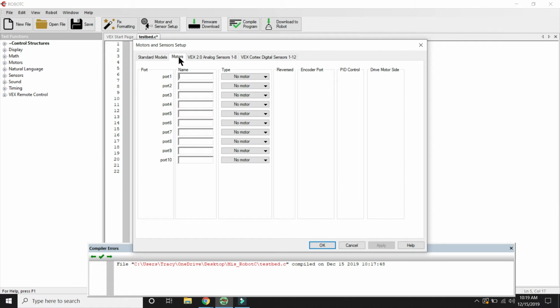So here's the thing. You always start with lowercase, and you can't put any spaces or any special characters, and you have to spell everything correct. So write R-I-G-H-T, motor. Remember, no spaces. So to symbolize a new word, I'm just going to capitalize the M for motor, O-T-O-R. So we put the right motor in port 1,